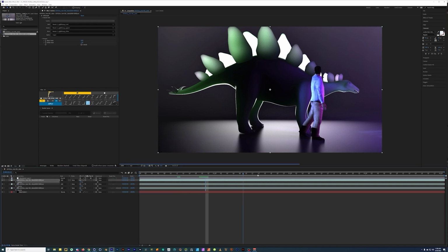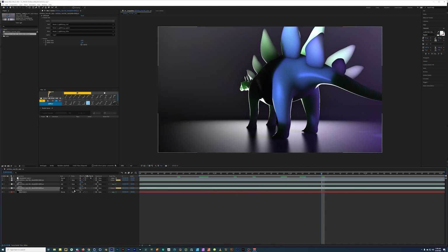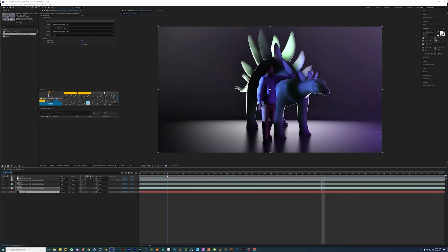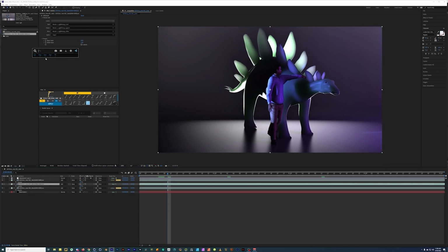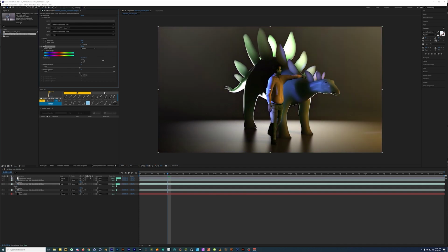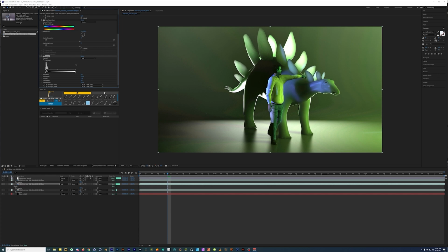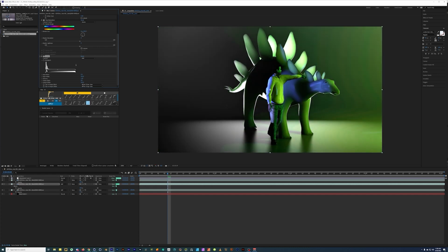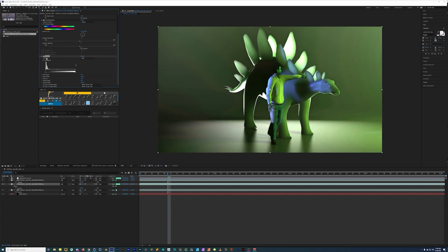So I haven't really heard too many people talk about that type of thing, so maybe you find that useful. But you can also do other things with the lights too. For instance, I can change the hue of a light, and so on. You can change the sharpness of it with levels. Just gives you a level of control that, who knows, might be useful. Say there was like flashing lights and you didn't know exactly where you wanted them to flash. You could render with them all the way on all the time and then flash them when you want to in After Effects. Same thing can be done in Fusion or any other compositor.